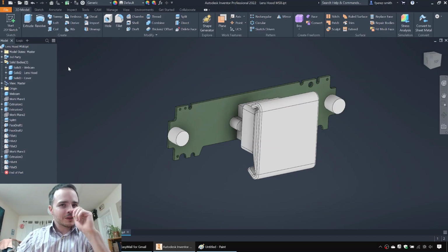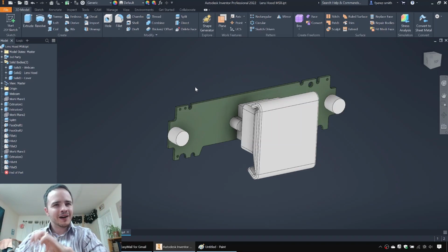So we've got a multi-solid body. Now we can't print this all out as it is because it will print all 3 components. So what we need to do is extract each of those bodies and make an individual part out of each of them.